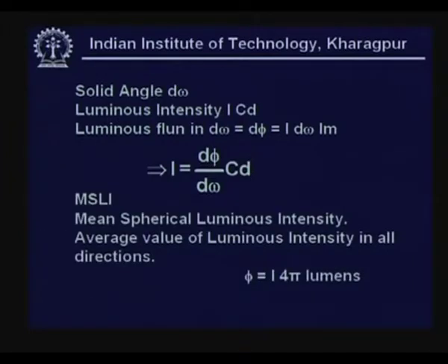Now, there is another term which we often use with respect to these lamps, because recall, after we started using electric lamps using thermoluminescence, it's been the incandescent lamps, which are nothing but a filament maintained at a temperature placed at the center of a glass envelope, which means it had the ability of radiating light in all directions. So, in a sense, it could be viewed as a point source of light. It had the ability of radiating light in all directions.